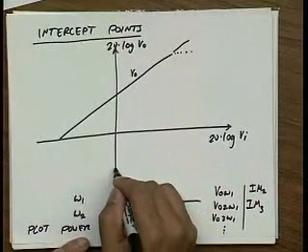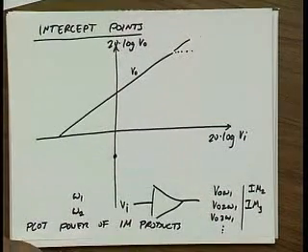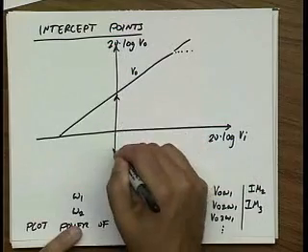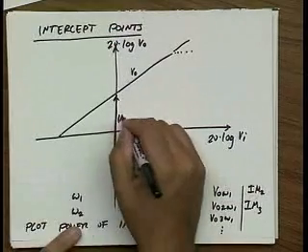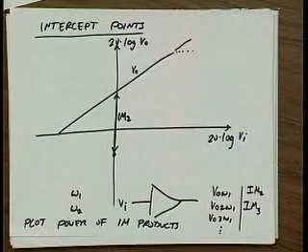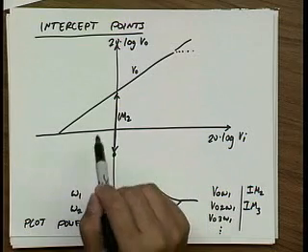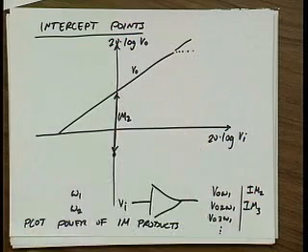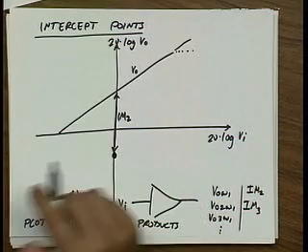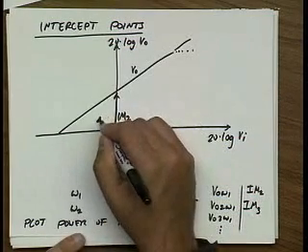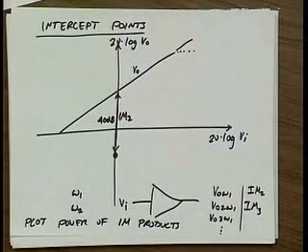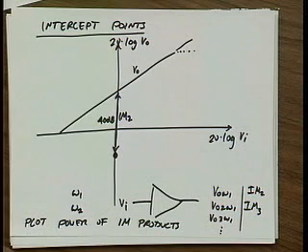Let's say I go out here and I measure that at a certain input power, my IM2 is down by this much, right? So IM2 is a ratio between the intermod component and the fundamental component. On a log scale, it's just this difference. Let's say that I find that, let's just say arbitrarily, this is 40 dB. That at a certain input power level, my intermod power is 40 dB down from the fundamental. Well, how does it vary with input? If I vary my input, what happens to this intermodulation component?